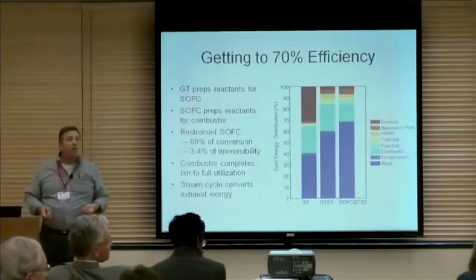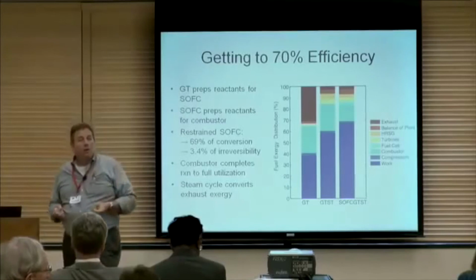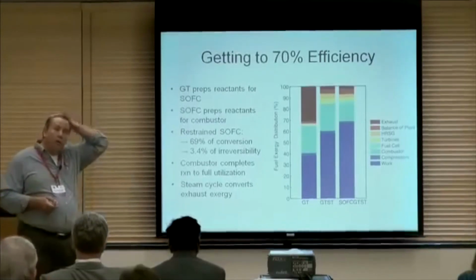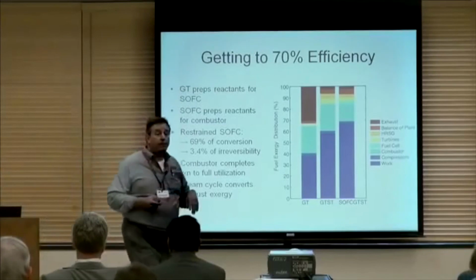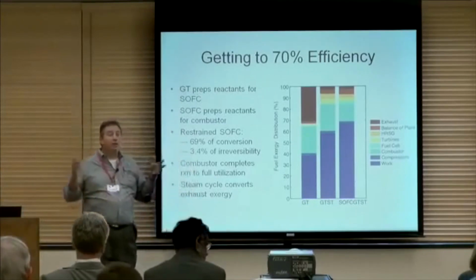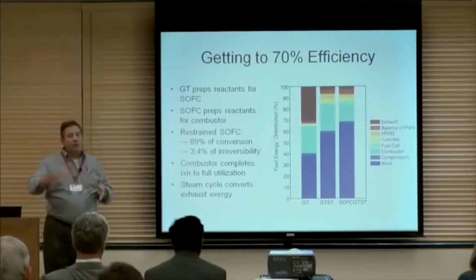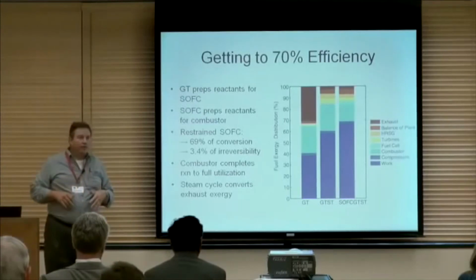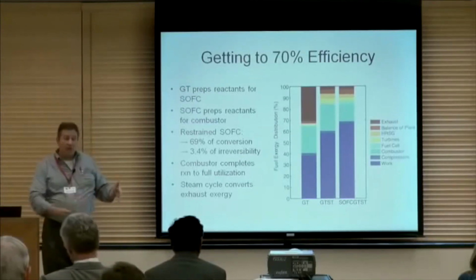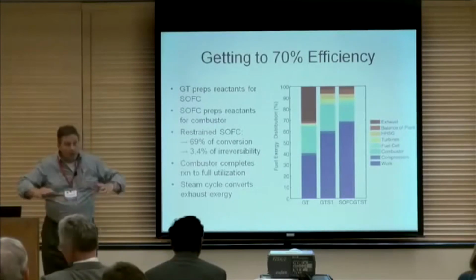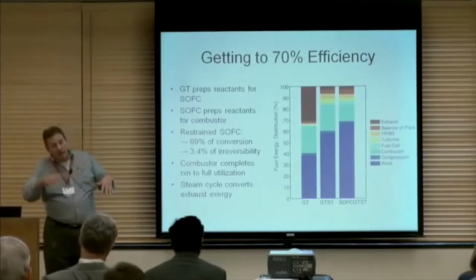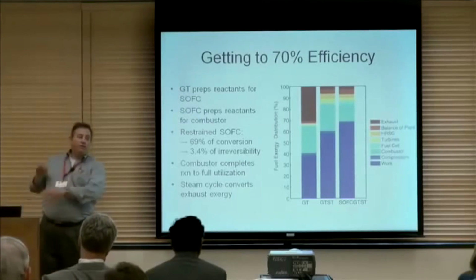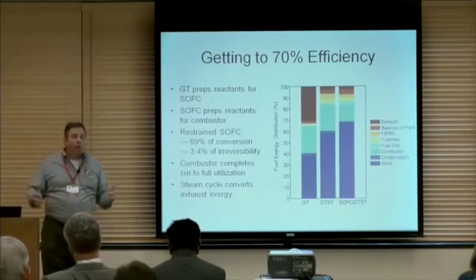Does that incorporate all of the steam reformation that has to happen on the LNG, or is that a hydrogen-only fuel cell? No, this is natural gas coming in. So it's internally reformed and anode recycled. You might have a small pre-reforming stage, but it's got a relatively big anode recycle, and we solve across the whole space to figure out where the best place is for it. And you break down the methane as you go to keep the concentrations up as you're moving along the cell. You play all the cards.